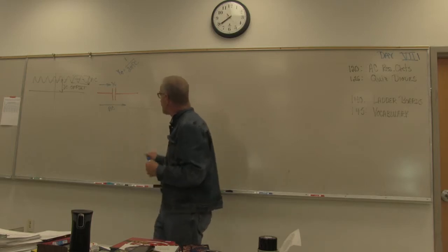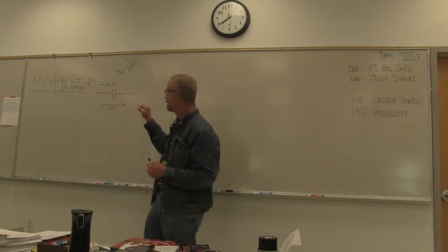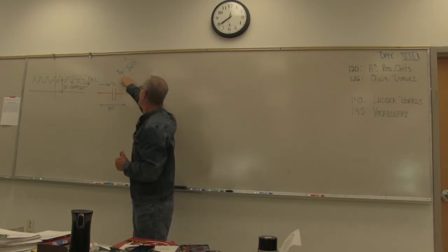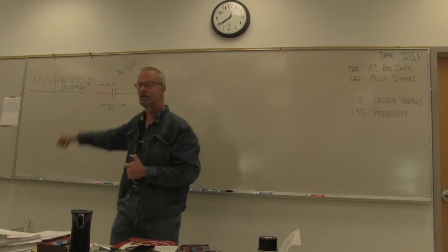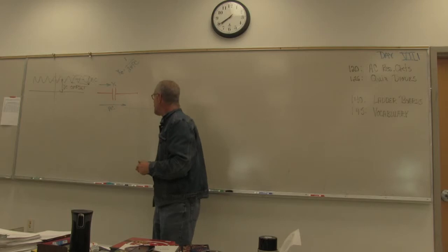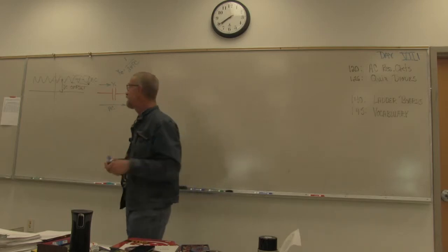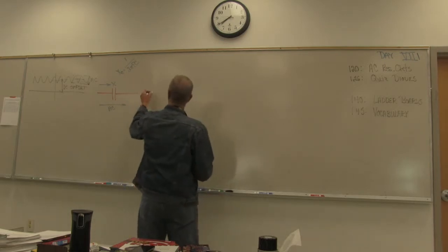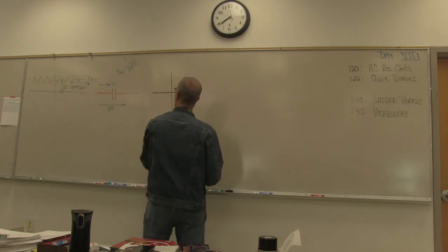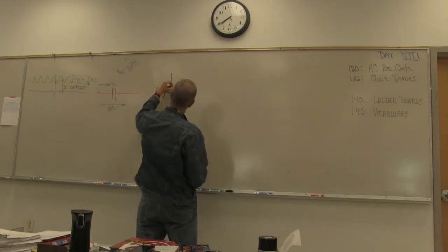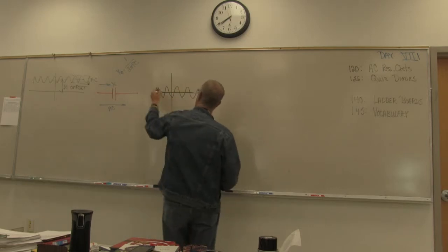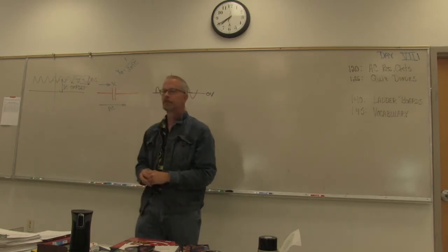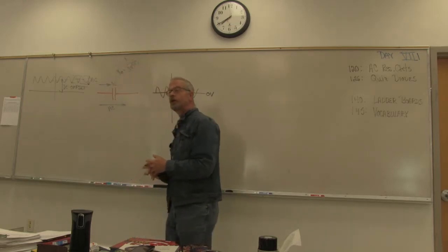So at a base level, a capacitor allows AC to go through it because it's higher frequency. But to a lower frequency, in other words, if there's a 0 here, then the reactance of that cap is infinite. So none of the DC should be able to get through, barring any leakage. So what that does for us is, over here, after the capacitor, what I'm going to see is the AC waveform centered on 0 volts by removing that DC component.